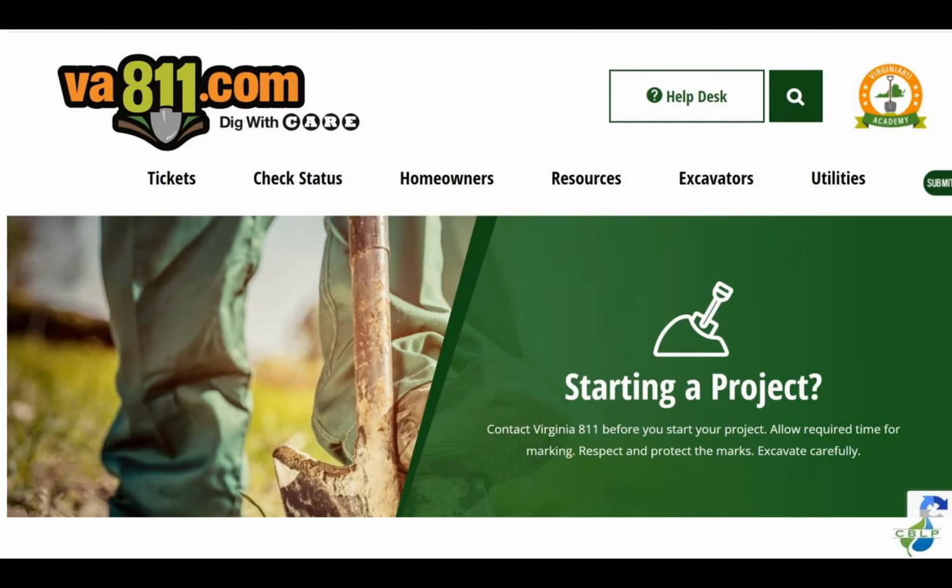Yeah, so of course, Miss Utility marks your non-private utility line, so it's a safety issue there. But let me backtrack slightly. When should you do this Miss Utility marking? It's largely up to how you want to do the process, or the district wants to do the process. You can always have it done before the site visit, just so you have more information when you're on the site.